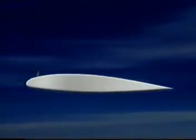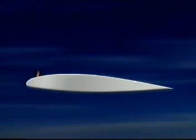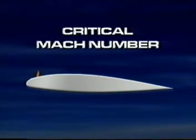But watch what happens when we accelerate the airfoil to speeds near the speed of sound. The local speed on the upper surface is higher than the free airspeed, and it is quite clear that airspeed over the wing can exceed or be very close to the speed of sound, although the airplane is still flying at subsonic speed. At a certain speed, shock waves start to form on the wing and the compressibility effects become apparent. The speed at which the shock waves first appear is the critical Mach number.